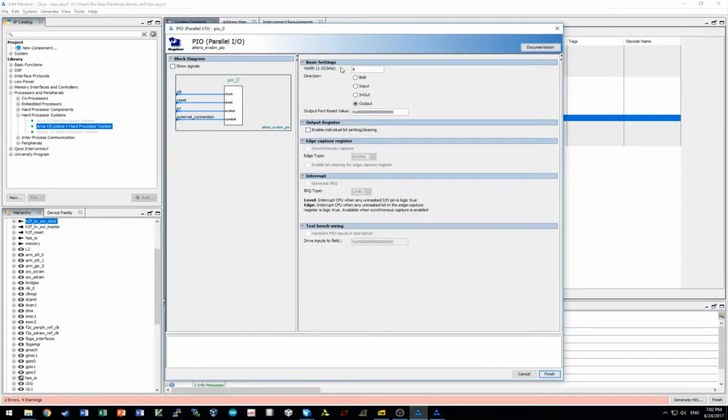Right, we have 8 LEDs. I want them to be output mode. It can be in-out mode or output mode. For in-out mode, you have to configure them to be output for the GPIO peripherals. And for the output mode, you just write to that particular bit, and you can set the output. So the output mode is easier to use, but you cannot read from that. Later we'll see the difference. So if you write your program in this fashion, I actually have the code already prepared.